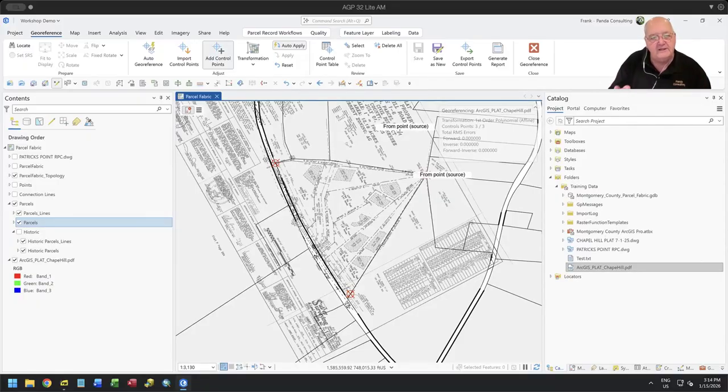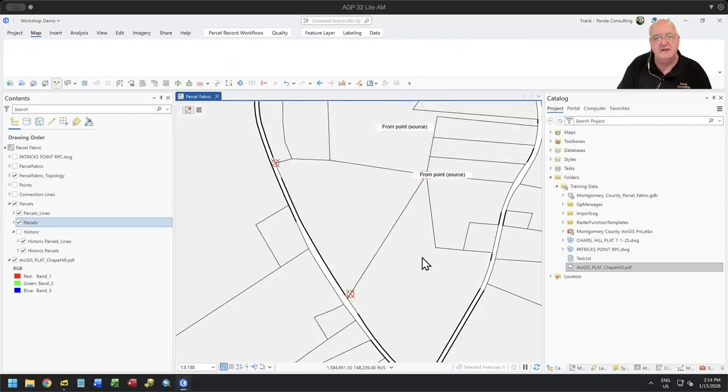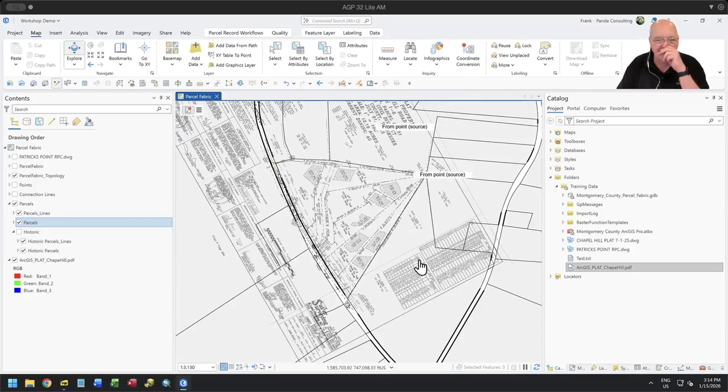It's created that georeferencing so that now I can take this out of my drawing and bring it back in. Whenever I bring it back in, it will read that world file and put it in the same place as it was before. Once I'm done with this georeferencing, I can say close this georeferencing, and it will close it out, and I'll be done with it.